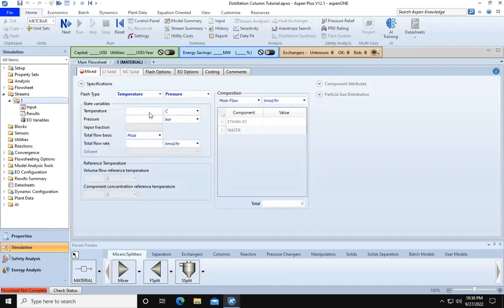And so for this, we have to give the temperature, the pressure, the flow rate, and then the compositions of our components in the stream. So for this, I'm just going to use one of the temperatures that was used for the column to heat the ethanol and move up through the stages. I'm just going to say about 200 degrees, because when you look at the vapor liquid equilibrium chart for water and ethanol, you start to notice more boiling around 190 up to 210 degrees. So I'm just going to go in the middle, use 200.